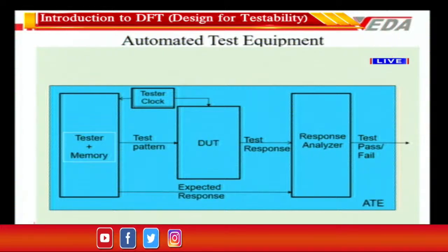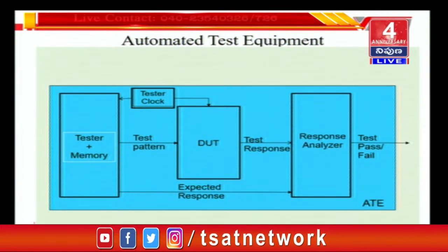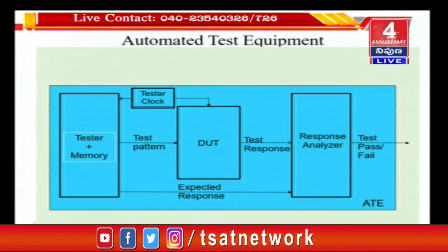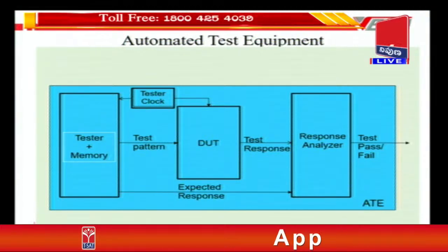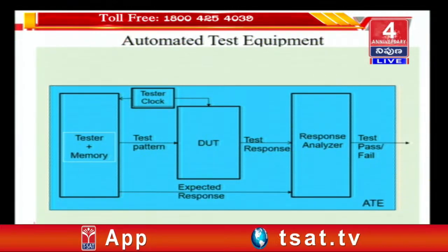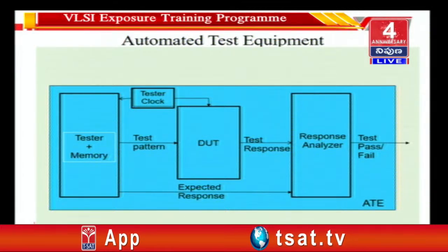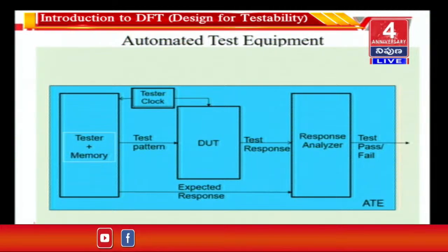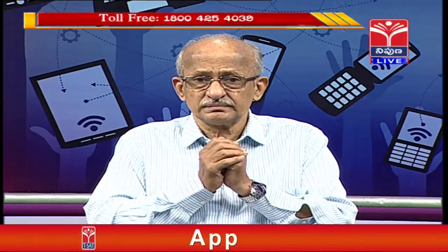Well, it is loaded into the tester by the manufacturer of that particular chip who is going to test. He or she has got a tester at their site. So, this tester is loaded with the patterns that have been developed by the DFT engineers and that have been provided to the manufacturer at the time of manufacturing.